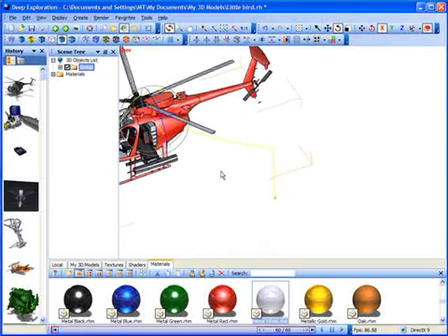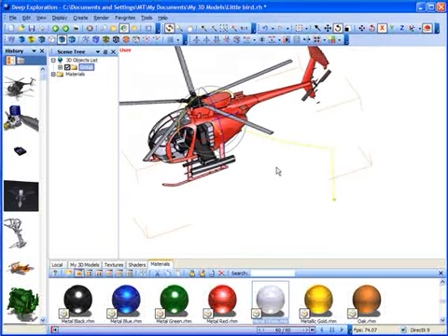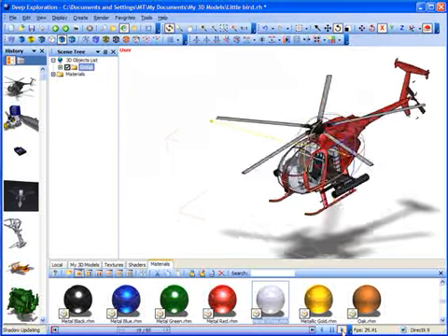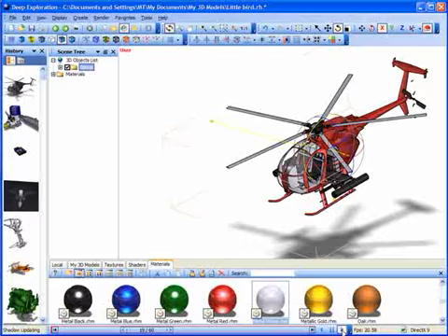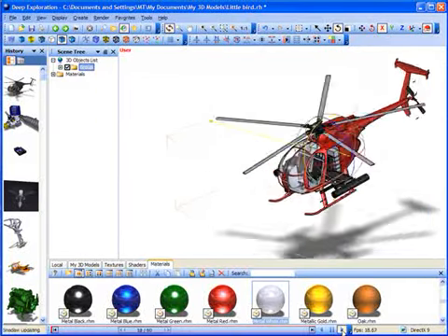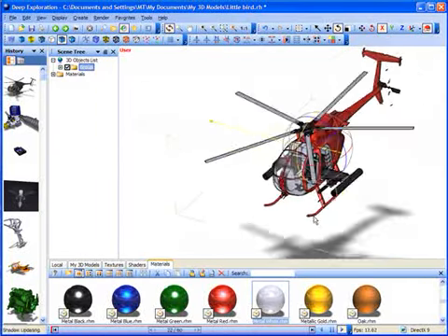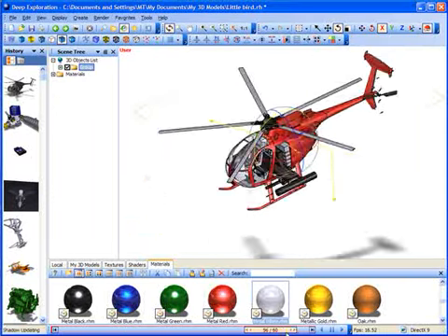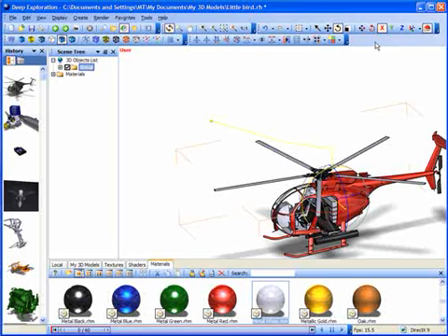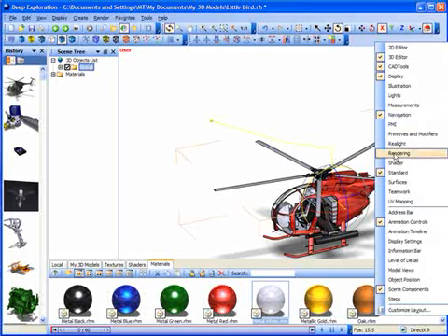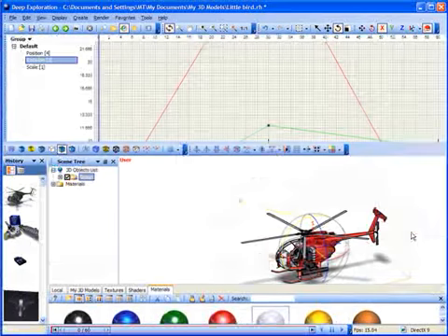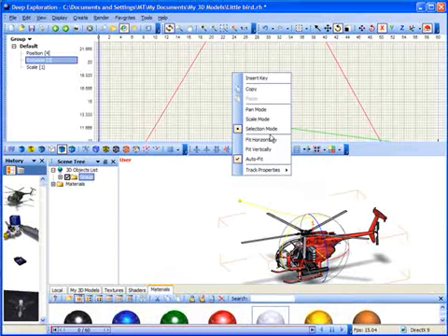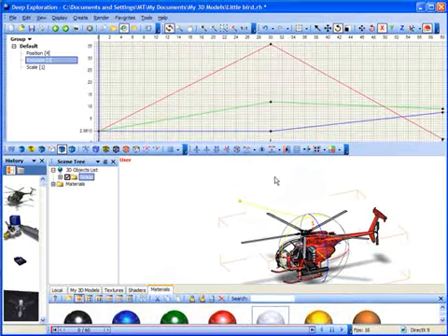Now we'll see initially that this curve that has been created, if we play back this animation, has sharp corners on the path, resulting in a less than smooth animation. Now to fix that problem, we can go to the animation timeline, and we'll see here that we have the entire path, and we're looking now at the rotation of this entire group.